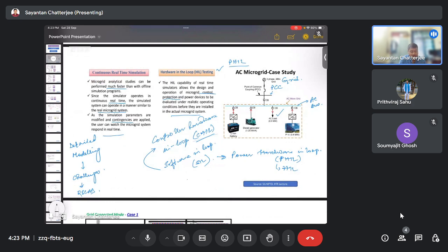Using those load flow solutions we can get the voltage magnitude and the angle, and using these we can restructure again to obtain the power flows in the entire system,